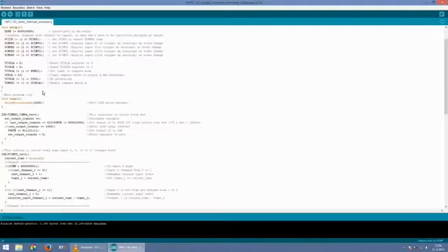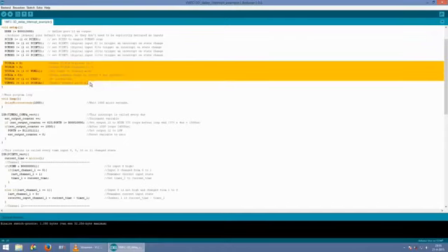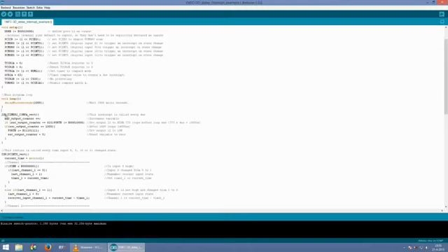Another way of creating a pulse is via a hardware timer of the Atmega 328. A hardware timer creates an interrupt whenever a certain value is reached. Now these lines set up hardware timer 2 to create an interrupt every 4 microseconds. With every 16 MHz clock pulse, it counts from 0 to 63. When reaching 63, this interrupt subroutine is executed.